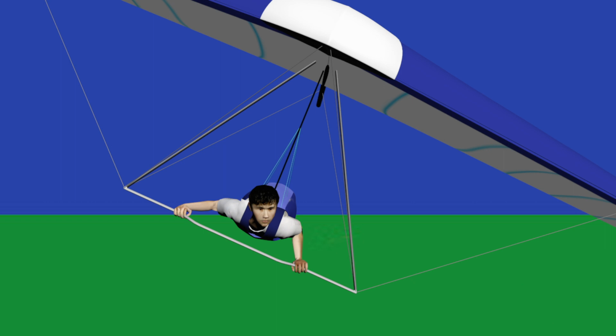Let's have a look at the forces that the pilot is experiencing at this point. First of all, there is a gravitational pull. The gravitational pull is always pointing vertically down. Then, because the glider is circling, there is a centrifugal force on the pilot, working horizontally outside. The resultant is the force the pilot is actually experiencing. This is why the pilot does not need to apply any force with his arms to maintain his position. The resultant is exactly at a 90 degree angle with the bottom bar.